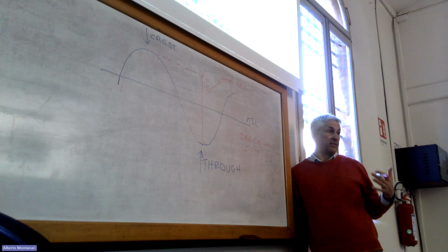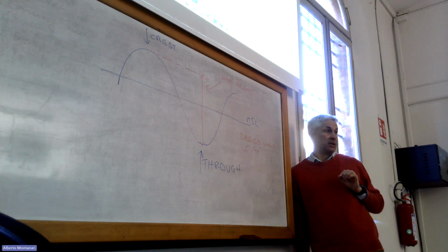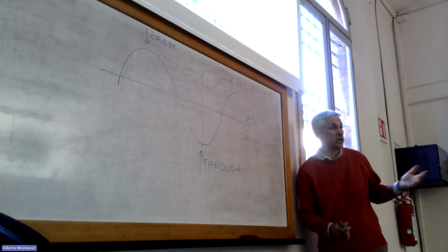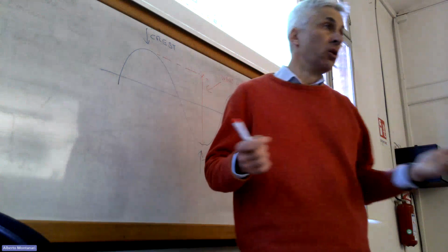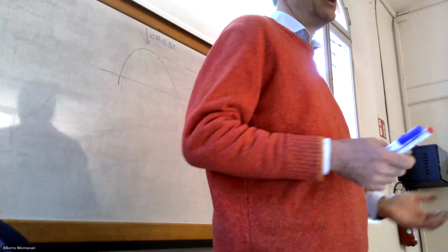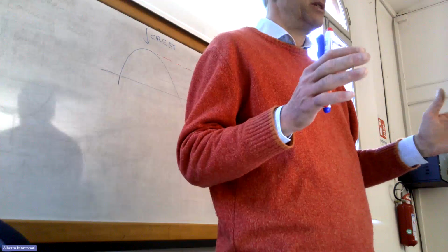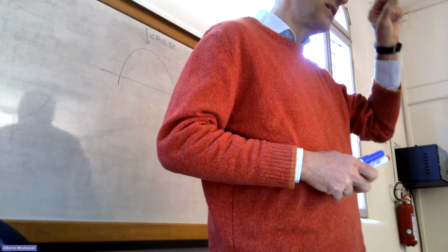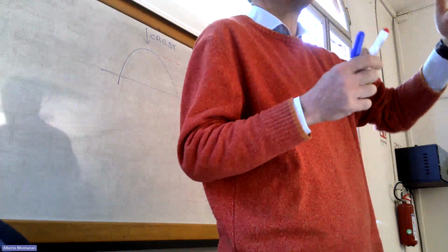And of course, why sometimes we are given monthly data? Because sometimes you specifically need to estimate a design wave that refers to a specific month. For instance, you may be involved in the design of a harbor that doesn't work during the winter, because maybe it's a touristic harbor. So during the winter, you don't have any boat, any ship berthed there. So if during the winter you don't have any use of the harbor, it's not required that you make your design basing on the winter design wave. You refer to the months where you are using the harbor, like from April to September.